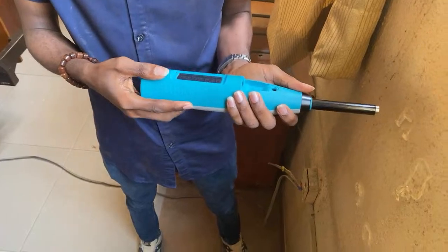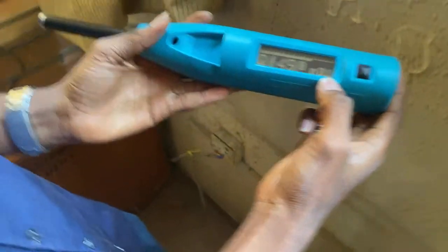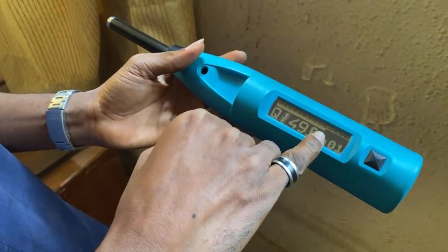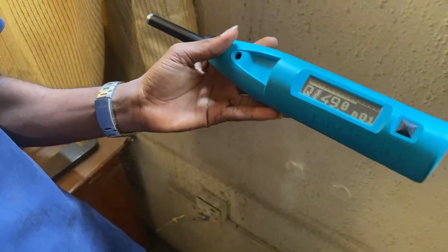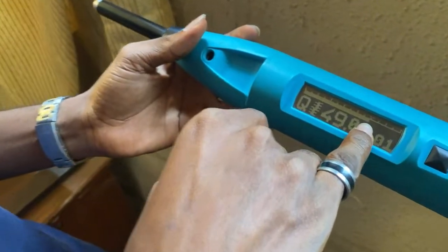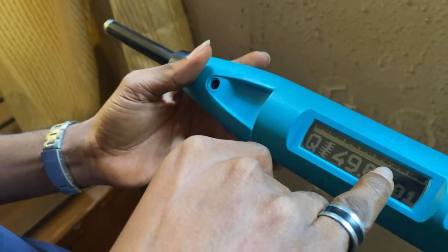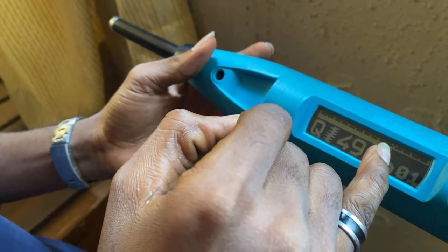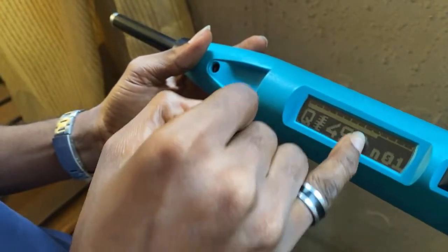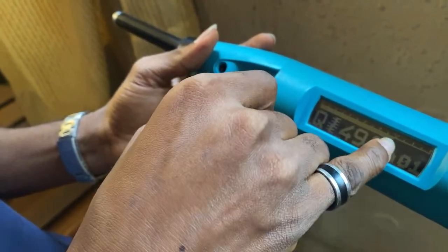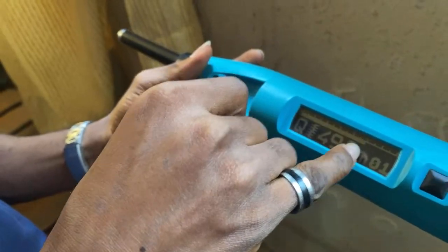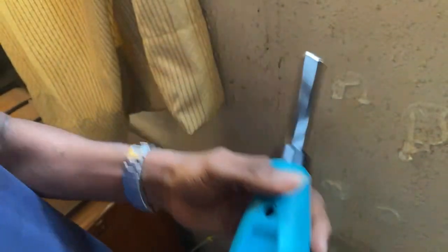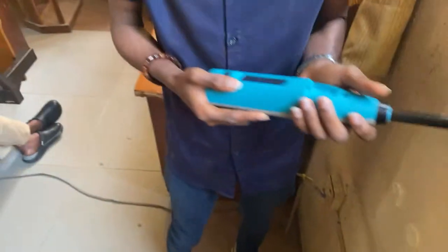That's one. Can you see? Number one, that's the first reading, then the rebound number. You guys can't see it, but I'll say it in the video here. You can see this place where we have 3 points. That's the 50th value. This thing is almost at 50, and anything exceeding 50 will be after this. So this is the rebound number, this is the Q value, then the impact number. That's for the first one.